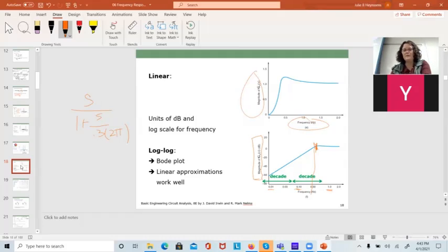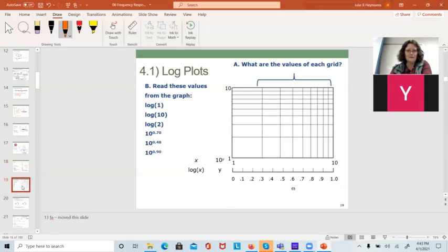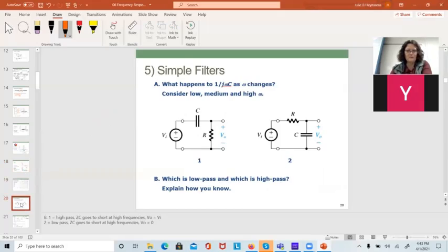An op amp actually looks like a low pass filter. Its frequency response is going to roll off at some frequency. 741s, it's a very low frequency. They're good for audio. That's about it. If that. That's kind of useless.